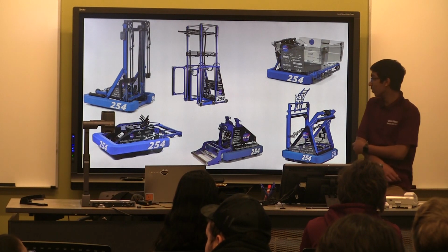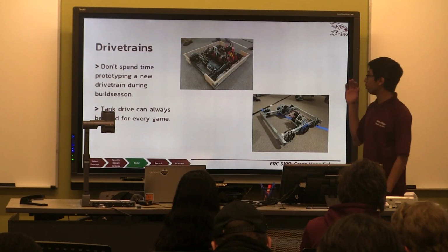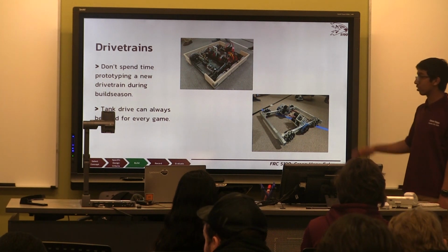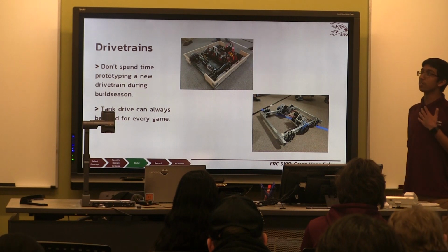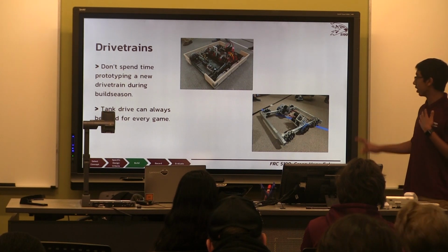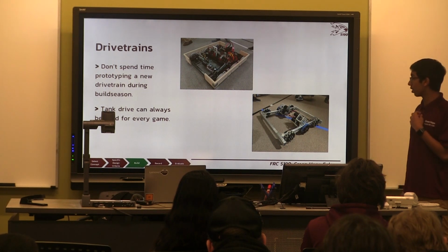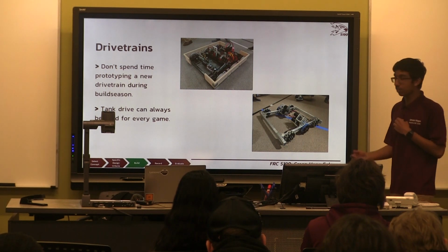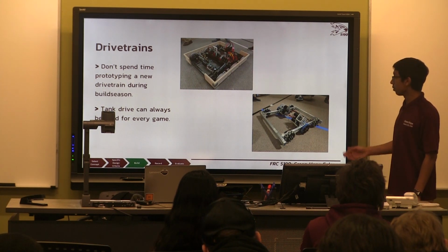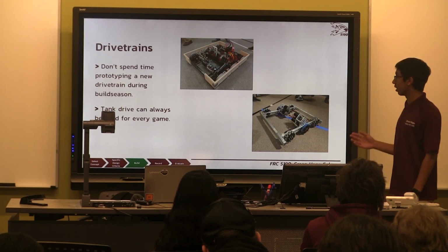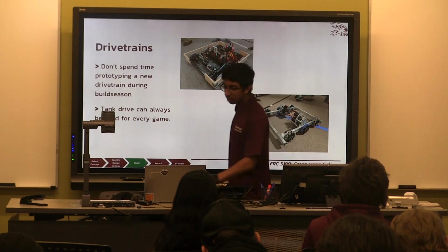West Coast. Yeah. So, drivetrains. This is one of the mechanisms you don't want to spend time prototyping. You know it works. Usually you'll never have to prototype a drivetrain, because I think our teams have used the same drivetrain and just changed where the motor mounting locations are for the past 4 years. And West Coast, there's no problem with it. It's easy to build, it doesn't take that long to prototype, and it doesn't take that long to assemble either. So just stick with West Coast or whatever drivetrain you're using for the next couple of years.